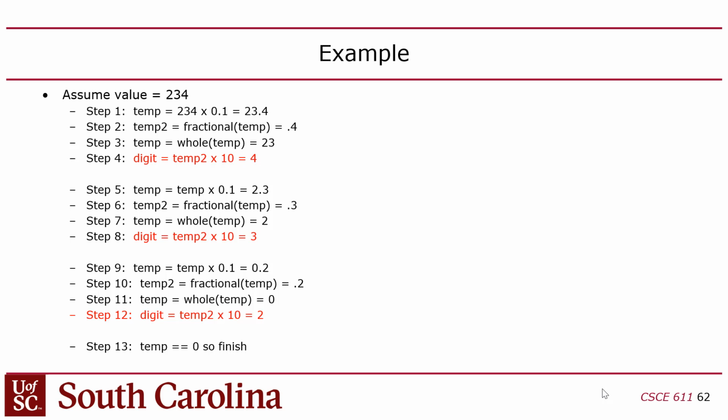Right? So in other words, if you take a 32-bit integer, right, and you do 2 to the 32nd power, which is 4.2 billion, right, and you divide that by 10 and put the value in the register, that will represent 0.1 because it's 0.1 through the whole range of a 32-bit number. You guys with me? Right? So it's roughly 429 million. That's your magic number that means 0.1. Okay? If you multiply that by an integer with 0 fractional bits, then you get a 64-bit result, but you only care about the upper 32 bits of that product, which are the integral bits, right?